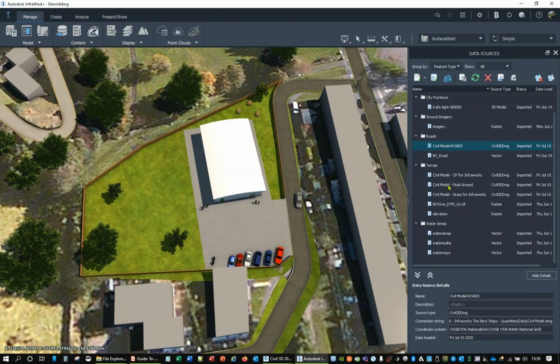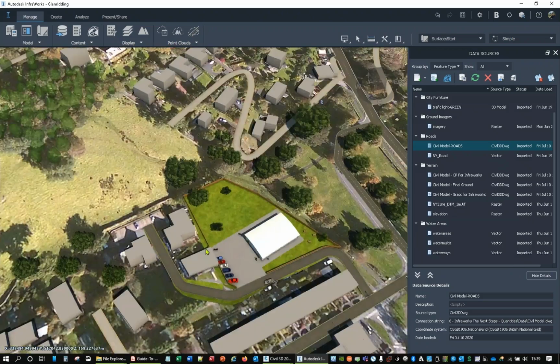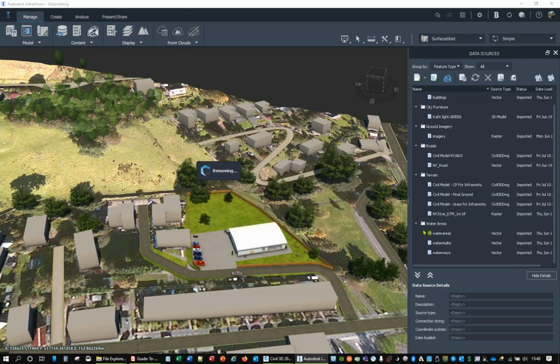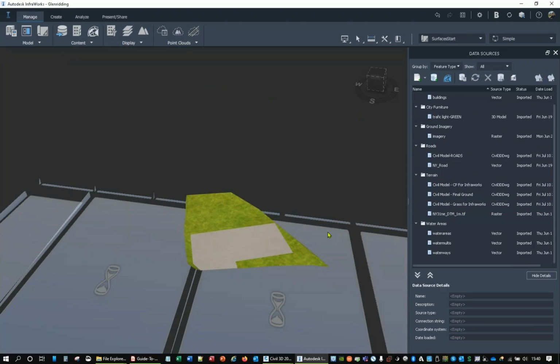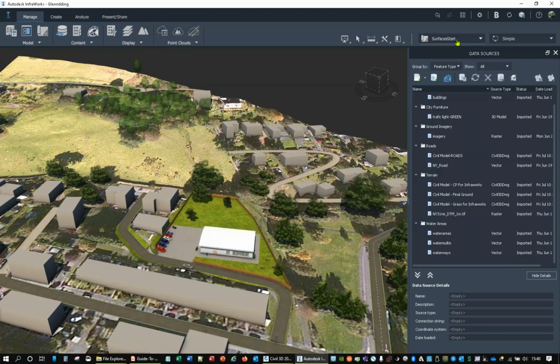A few tips on working with the extra surfaces. I think the key takeaway in here is remember that there's an order which it creates things. The other thing to bear in mind, just to keep your models smaller, if you don't need that original data, delete it. Now, if I delete it from here, in this proposal here, it will make my model a bit smaller, which is quite nice because I don't need it, because I've got the LiDAR data that I got from the Environment Agency. But of course, using these proposals, it can still be there.